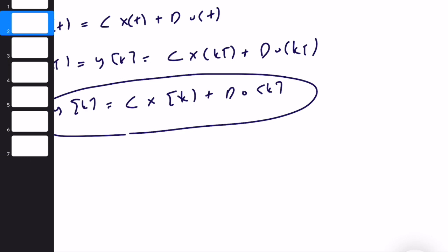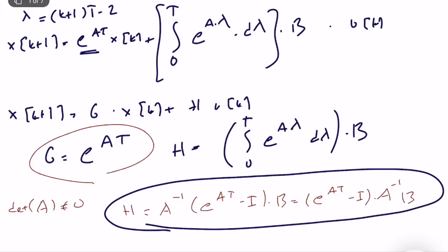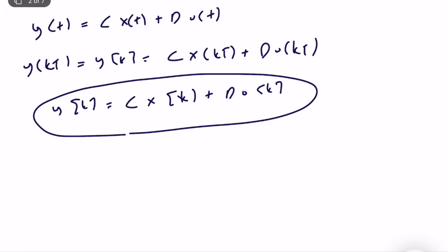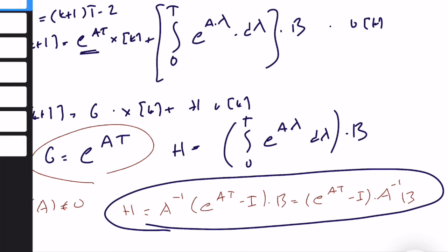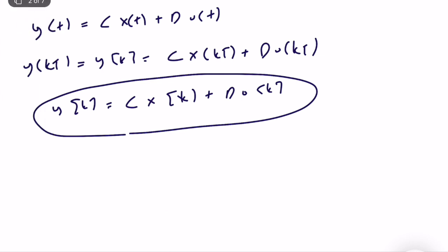Of course, there are important computations that you need to do for the G and H matrices, the system and input matrices, but the output equation is not changed if you're not changing your definition of output or type of measurement. Of course, instead of sampling the states, if you come up with a new discrete time state definition, you may also need to change C and D. But if your plant is given in the state space domain, and if your goal is to obtain a state space discrete time structure, this is the best formal and easiest way of computing the state space approach.